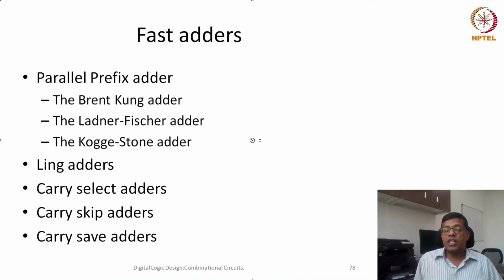Other than carry look ahead adders or ripple carry, which are the basic fundamental techniques, using those techniques, in carry look ahead we have seen that carry can be generated in parallel by looking ahead. Basically we can have a carry for some individual blocks, and then we can use the other blocks' carry to finally generate the final carry. All these combinations are what we call parallel prefix adders. Why parallel? Because now the carry is being generated in parallel, so they are called parallel prefix adders.